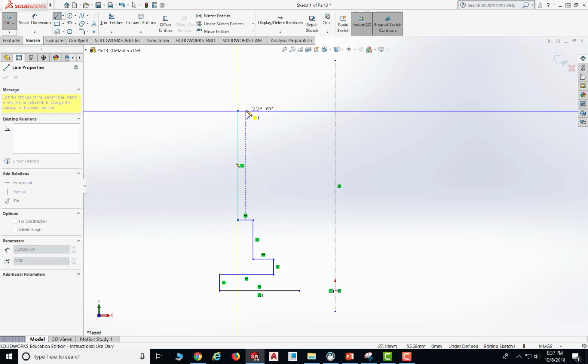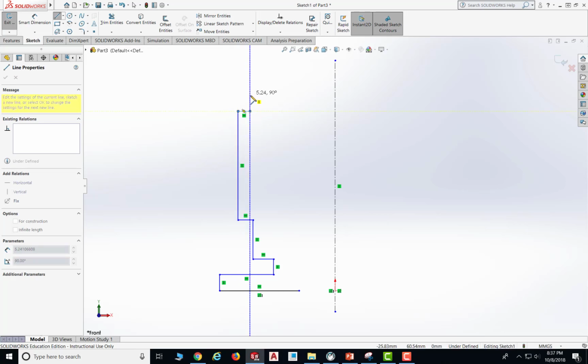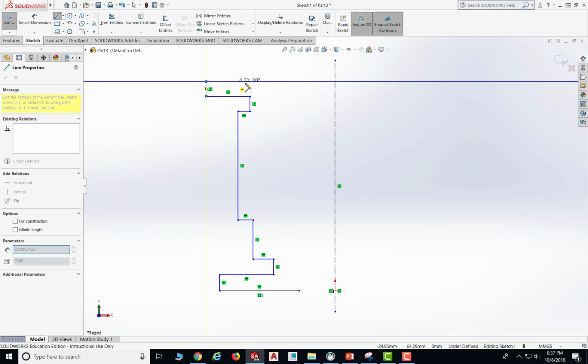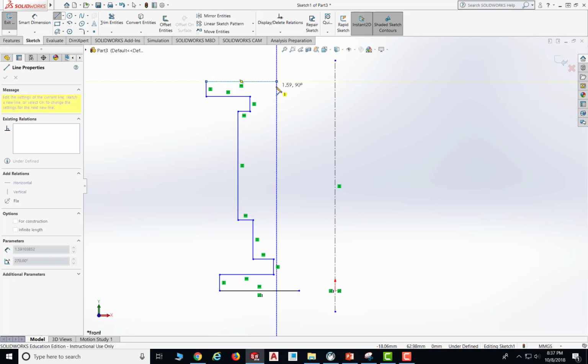and you don't want to pick the center lines here, so just normally draw the contours, because you don't know if that's a center line. If you had that relation, then you would have to delete it later, otherwise it will tell you it's overdefined or something that you don't want it to handle. Anyway, so draw the contour here. So don't pick the center lines. And here looks about right.